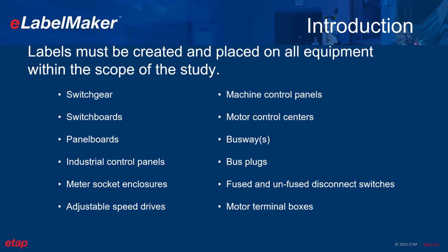Each of these fault locations has different incident energy values and corresponding safety symbols, and the incident energy, the arc flash boundary and the units, or sometimes shock risk assessment boundaries, are also included in the label. So this opens up a challenge for creating different label templates and meticulously showing the incident energy analysis performed by ETAP.